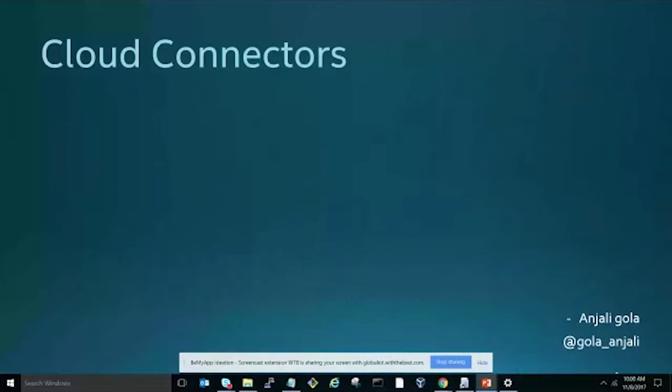I'm sorry, I'm not able to pronounce your name correctly, but someone comments that through this conference, a likely strong blanket solution would be having devices such as Arduino reporting sensors to a local edge device so it can be stable. The edge device would sift through all the sensor data and decide what actually goes to the cloud, and the edge device could more easily be upgraded. Is that a good train of thought? It is a perfectly good train of thought.